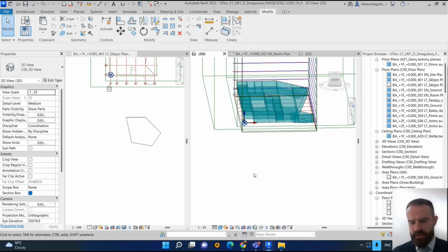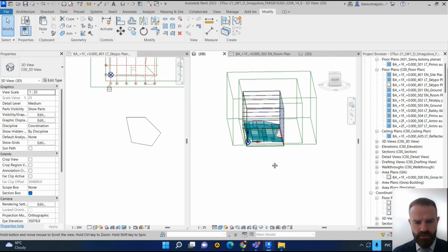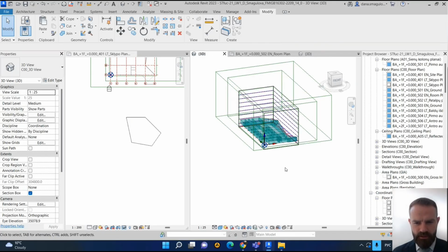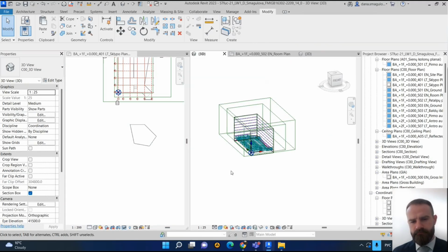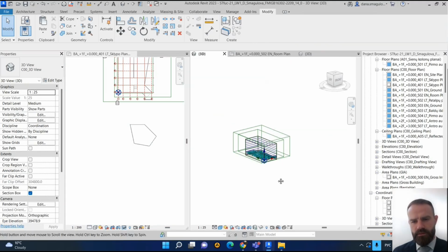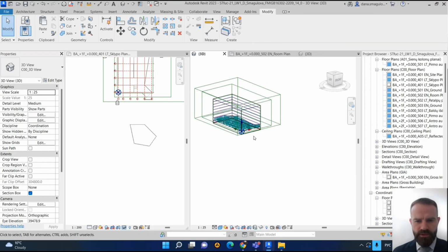So remove in 3D, turn off the section box in 3D. Turn off section box in properties. Go to 3D view. Now on the properties, move mouse to the properties and turn off the check mark from the section box.